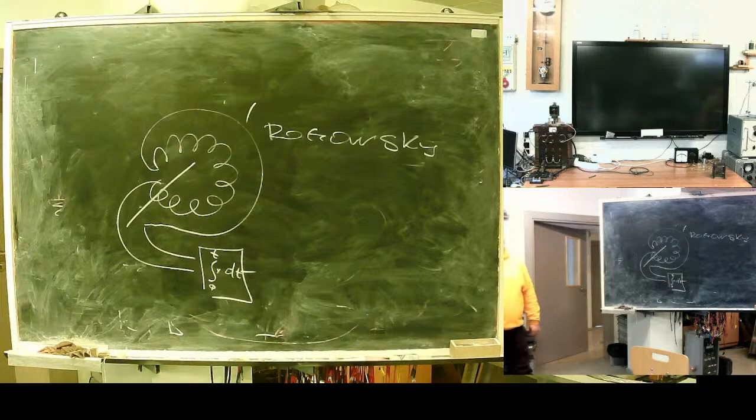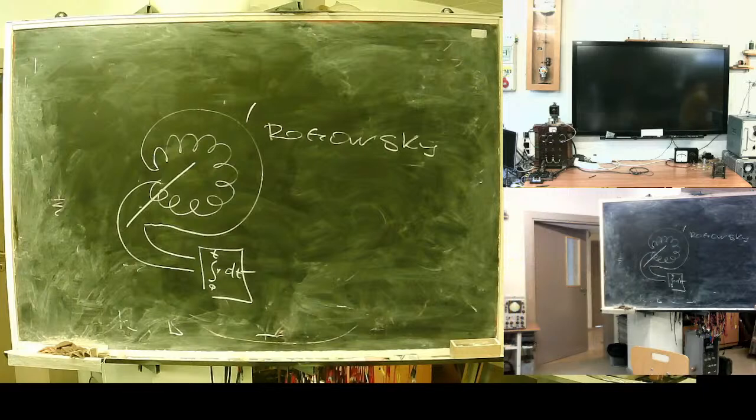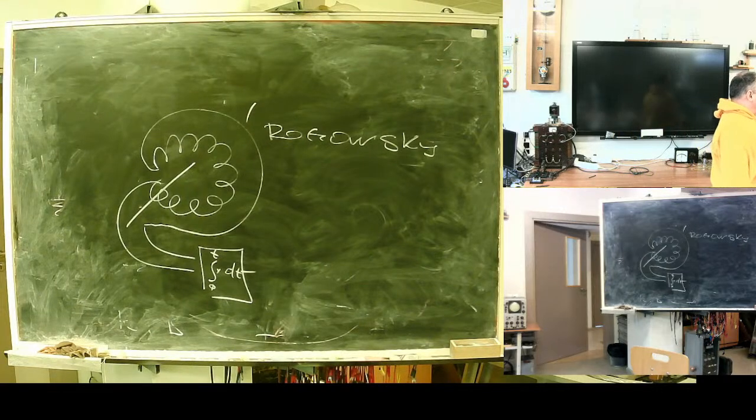Whole switchgears exist with Rogowski current sensors. A Rogowski coil works only with the relay it's intended for, because it needs an amplifier and integrating. Be careful with Rogowski coils, they have zero load capability.